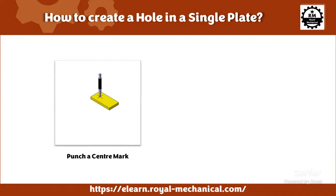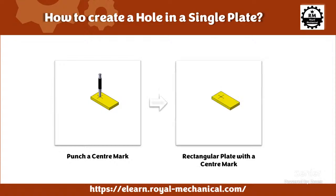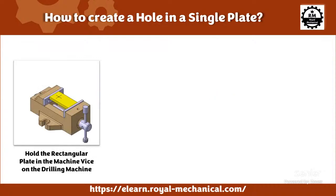So once you identify this intersection point, this is where we need to drill the hole. To drill the hole, we will have to make a center mark using a center punch. And then this is what we end up with. So we have a rectangular plate with the center mark, which we'll be using for drilling.